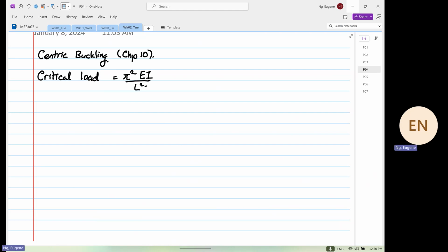Now, this is at the edge of collapse. Okay, I want you to focus on what will happen when it's collapsed. So this is heavier. If you focus on this end, it is going to bounce outwards. Okay, so if I were to just bounce it, you can't see it properly down here because it's holding. It's going to have this sort of bellowing shape. Are we clear? That's where you see buckling.